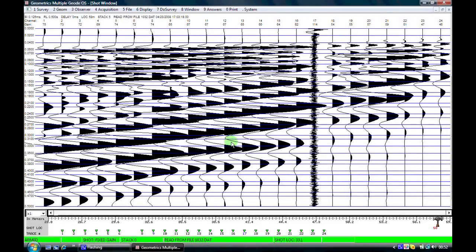This slide is a typical seismic refraction record, which I will now explain, what we're seeing on the screen. Across the top we get our geophone numbers from 1 across here to number 24. The second row, which we'll see later as we make some adjustments, is our trace scaling factor, which is applied to each of the geophone channels.